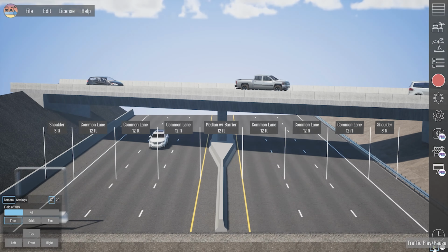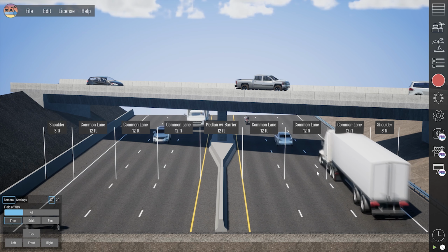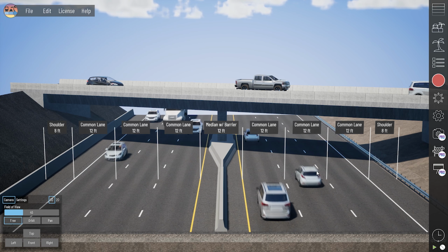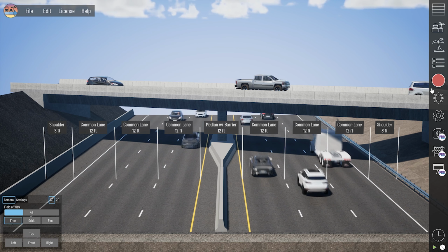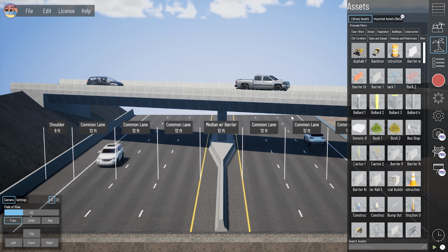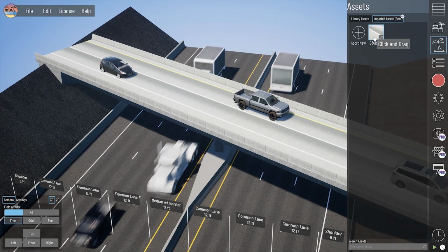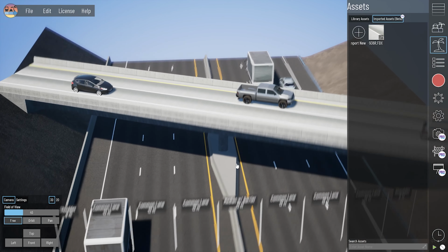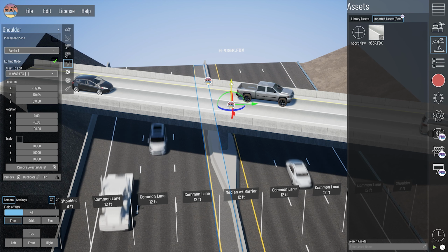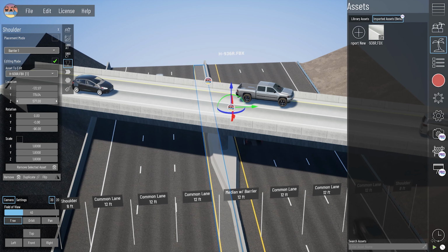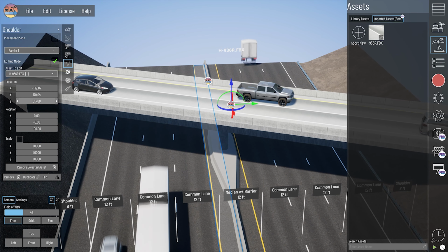This is the highway median barrier example project. We put this one together to show that there is the possibility to show things like overpasses on your typical section, but that does require importing assets. In this particular project, it comes with an imported asset here of this bridge type, where you can see it's been brought in and placed on the central median here, and that is effectively just its own 3D asset piece, which we've centered on the typical section.